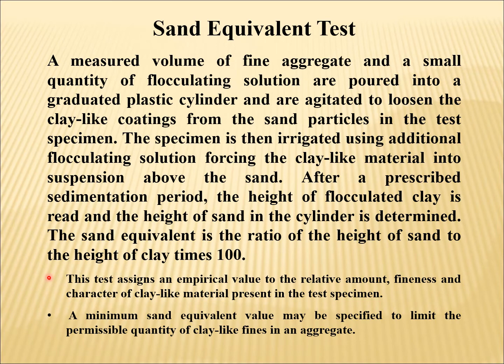This test assigns an empirical value to the relative amount, fineness and character of clay-like material present in the test specimen. A minimum sand equivalent value may be specified to limit the permissible quantity of clay-like fines in an aggregate.